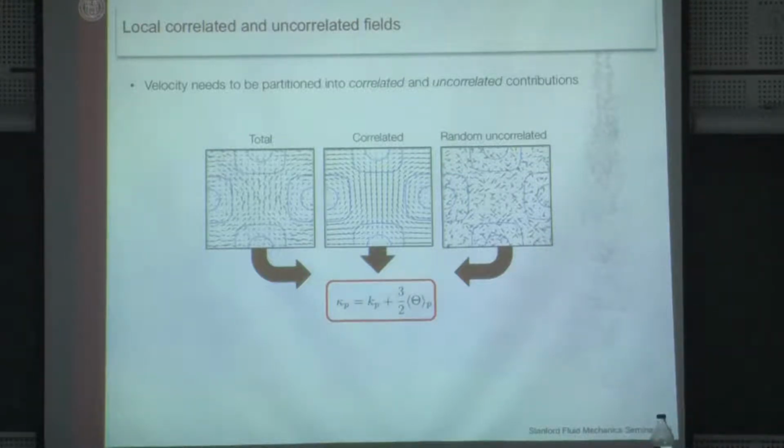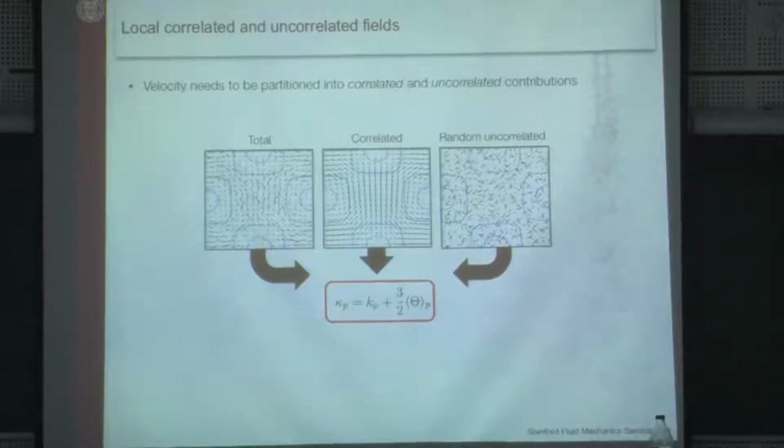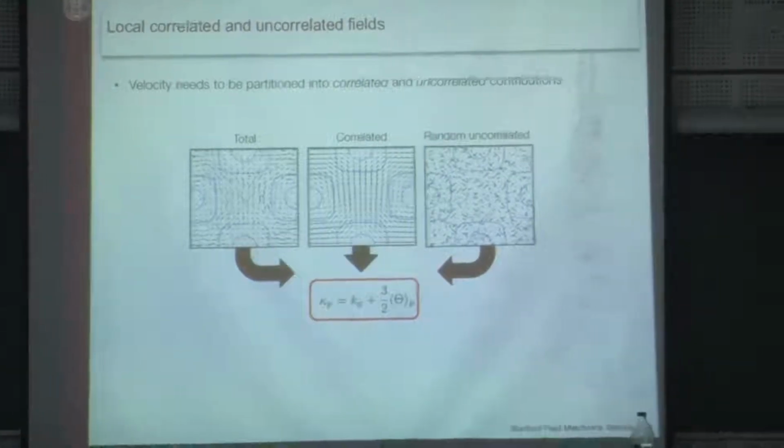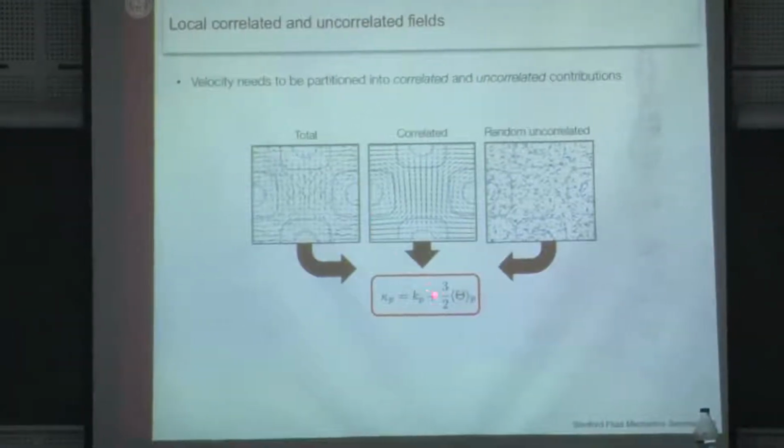They have different velocities. I can average that velocity and have an equivalent Eulerian velocity for my particle phase. Well, that velocity is going to be my coherent particle velocity. This can still, however, fluctuate. There's still going to be fluctuating energy in that because the flow is turbulent. So that's going to be what we're going to capture here in this Kp.